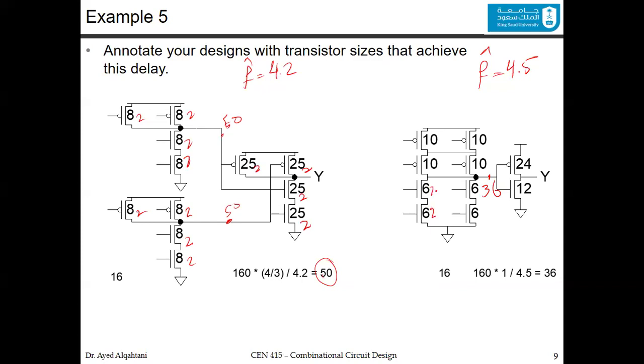So it's 2, 2, 2, and 2, 4, 4, 4, and 4. And the last one is 2 to 1. That's the simple inversion. What you do is distribute the 50 to both of them. And we know it's 50% in the NMOS, 50% in the PMOS, since it's 2 and 2. And to do this, we explained in the previous video.